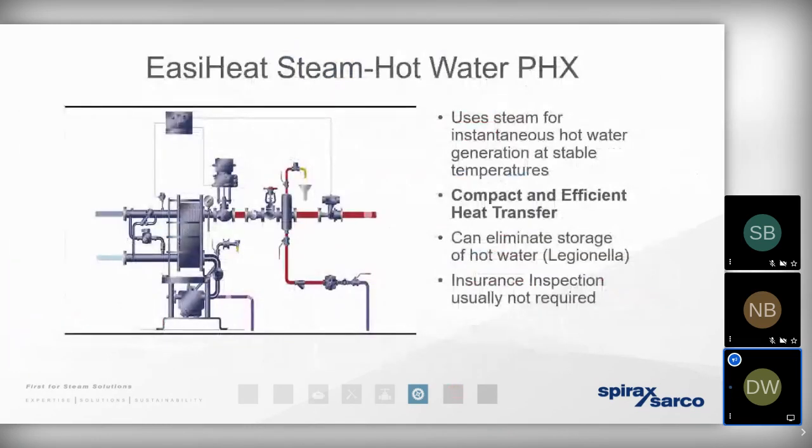So we also know that we may be encountering issues at the process, at the heat exchanger, due to poor heat transfer. Now, it may actually not be down to any fault of the steam. The steam condition may be perfect. It could be down to the fact that we're simply not removing the condensate. And if that condensate backs up ahead of the steam trap, it could slowly start to flood the steaming space. And as we know from that previous slide, there's significantly less energy present in a mass of condensate. So of course, if the steam cannot enter the heat exchanger, the rate of heat exchange is going to slow down significantly.